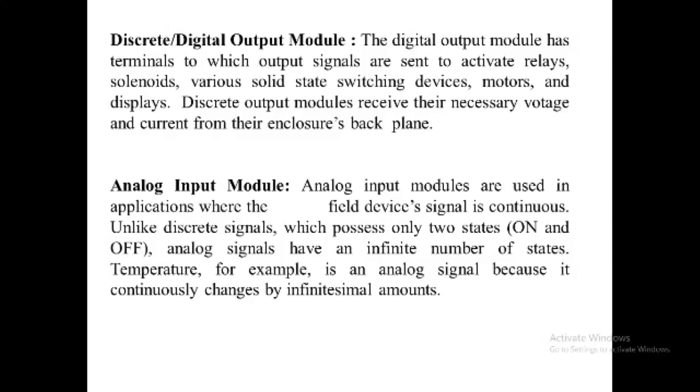Furthermore, an AC output circuit may contain a fuse that prevents excessive current from damaging the switch. And if the circuit does not contain a fuse, the user should install one that complies with the manufacturer specification.